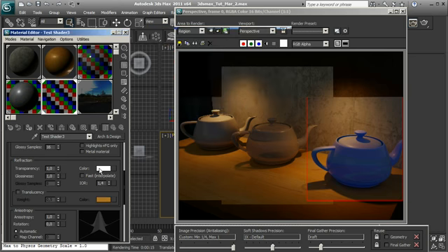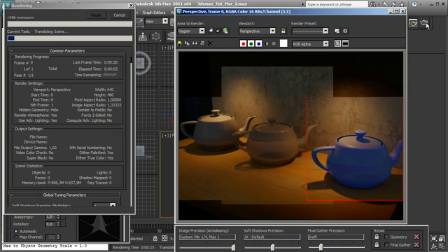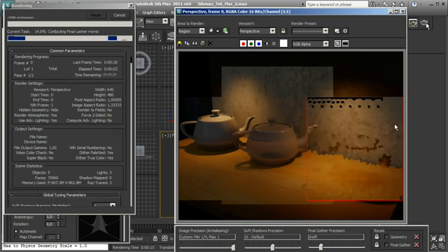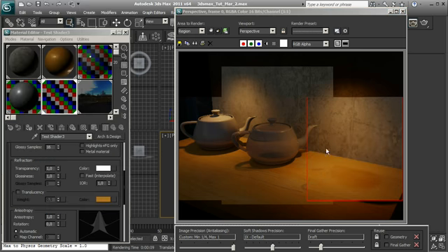Okay, we have the possibility to control the glossiness also for the refraction, but we'll see later how to work with it. Let's see the IOR. If we use 1, for example, and we try to render again, we'll have no distortion for the refraction, and you'll see that it is something like a ghost effect, because we can see perfectly all the things we have beyond the teapot.